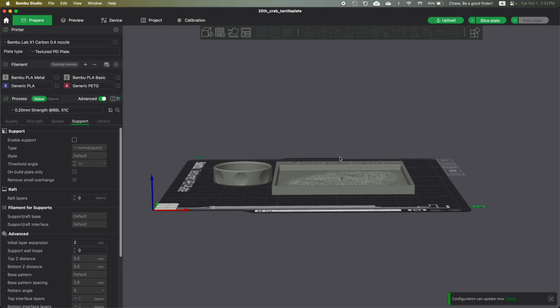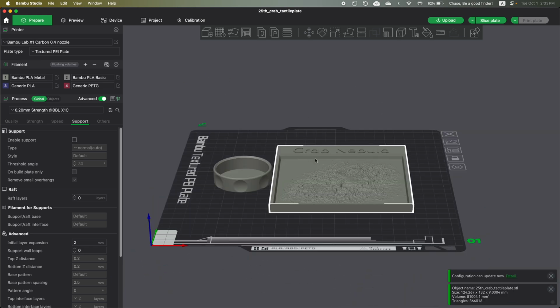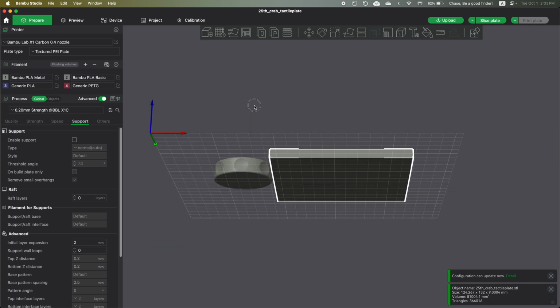So you don't have any weak features that are in the Z direction. I hope that makes sense. You'll understand that as you go and experience 3D printing for yourself. So make sure you rotate the parts so that they have the best layer orientation and so that they don't fail. You want to have a good contact with the print bed.